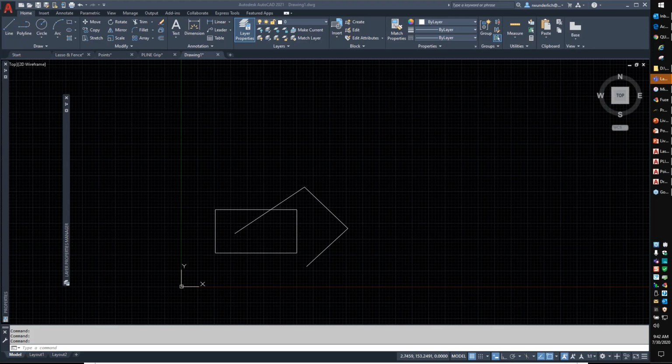How do you set data links to auto update? They normally should auto update, but if it's prompting you to update, that usually means you're running into the plot, where it wants to auto update prior to plotting. The data links normally propagate whenever you open the drawing after it's been closed. But if the drawing's been modified, then you do have to go back and force an update.